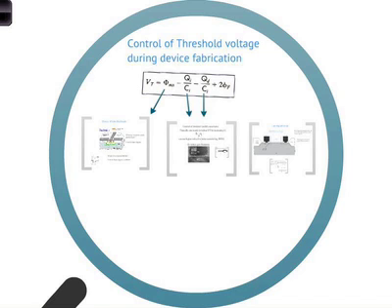You will get anomalies, all that kind of stuff. Also, you don't want the transistor just be on and you'll have leakage current and you'll have power loss and your battery will die off. You'll get heating and all that kind of stuff. So the choice of the threshold voltage is very critical in an actual working, practical application. And there are a few things that a device designer can do during the fabrication of the device to design for the threshold voltage. This is very important.